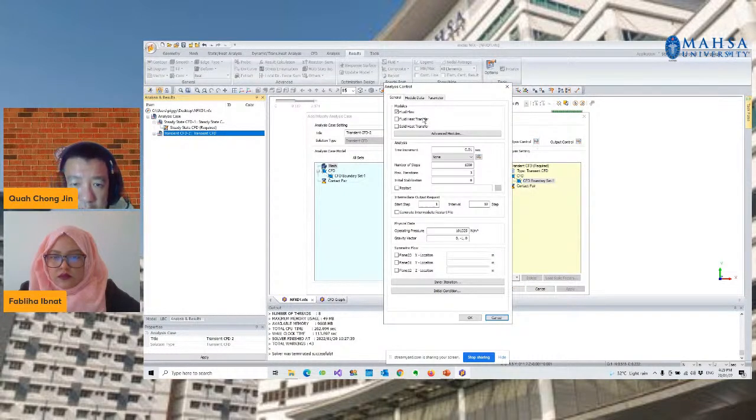Let's check my setting. Okay, so I'll just put any value for the number of iterations instead of 1000. I put it at 5000. As I mentioned, we were not able to know the number of steps. If you have been exposed to FEA or CFD before, I'm sure that you understand what the number of steps is. The number of steps is very important in transient mode instead of steady mode. In transient, you have to determine the number of steps required and the delta t, which is the time increment, that you require. So we put everything at default without changing anything.